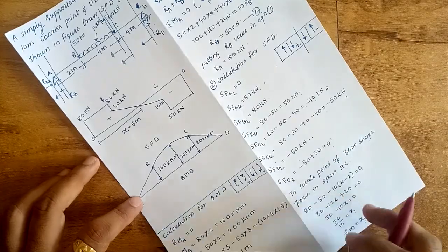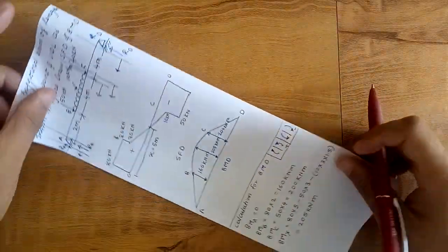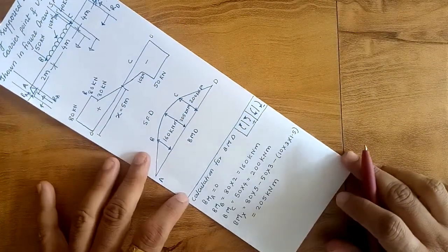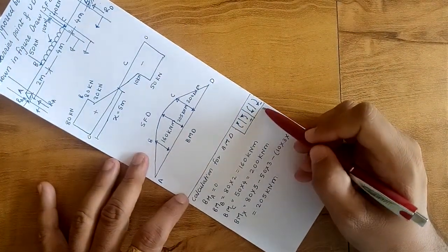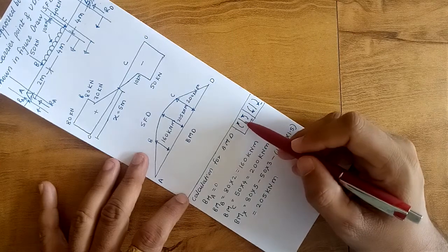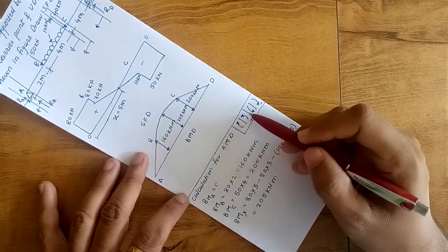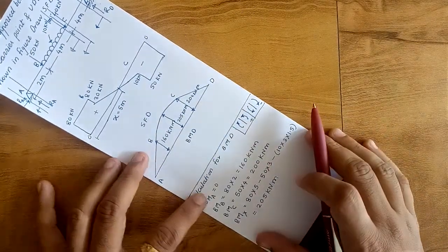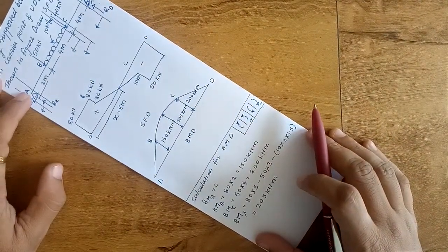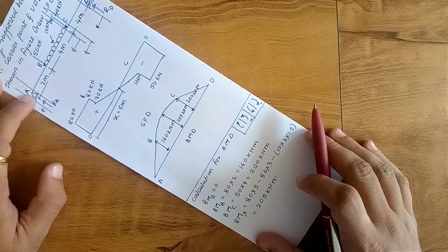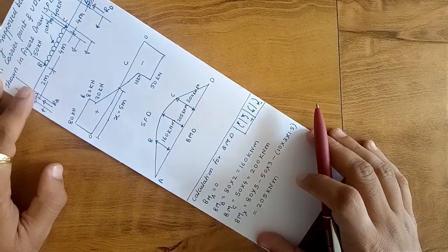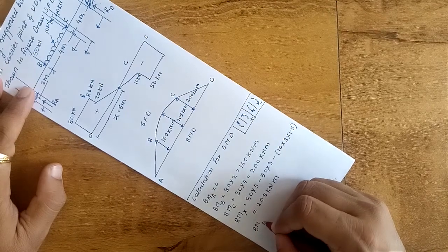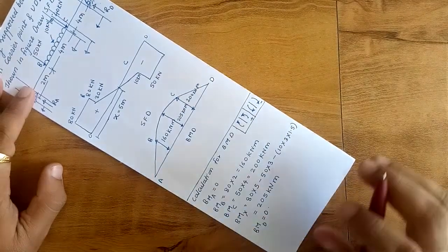So we know x is 5 meter, and for calculation of this bending moment, I have given here that we have considered the sign convention. Clockwise is positive and anti-clockwise is negative if it is toward the right of a section. So these are the sign conventions. So bending moment at A, as I have already told you, this is the pin support, so definitely the bending moment at A is nothing but 0. And bending moment at point D will also be 0 because it is a roller support.